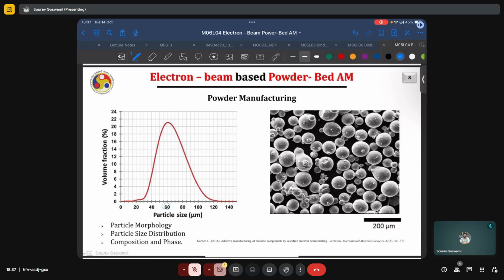While it is possible to control the distribution or width of this variation, it is not really feasible to have powder particles of only one given size, or even if it were somehow possible, the costs would be truly prohibitive, and such powder feedstock will not really be usable because of the very high costs. Gas plasma atomization typically gives us the tightest control over this powder size distribution, and it goes down as we opt for other methods.